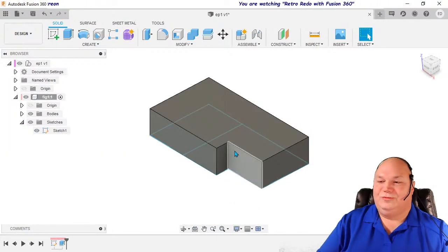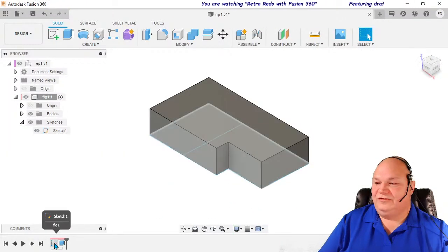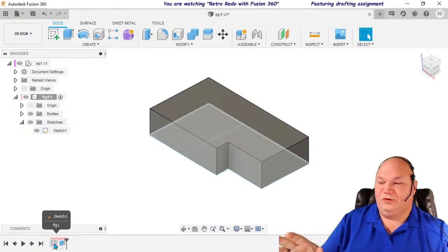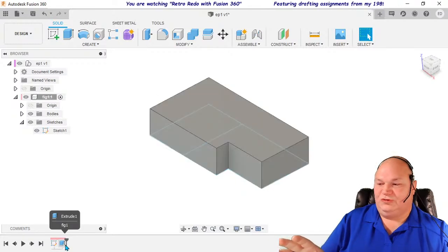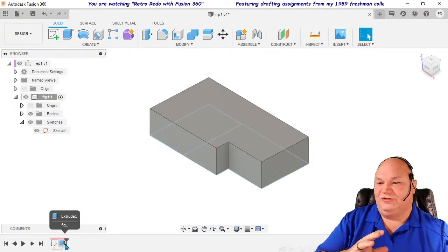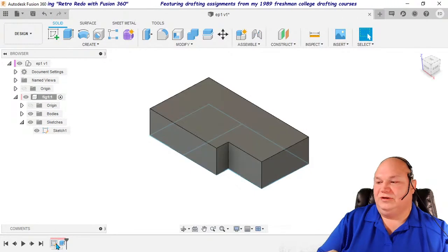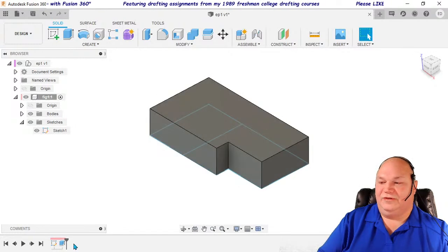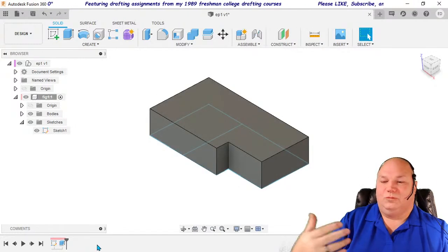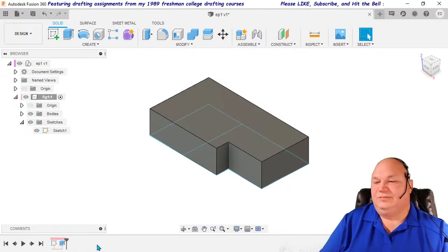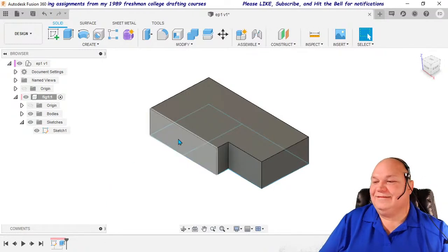And so see, we just went back and edited the sketch here in the review. This is the history of all of the changes we're making to the object. So if we need to change the size of this later, we can come back, edit the sketch, and all of the things that we've done after that will follow most of the time. It's always most of the time.